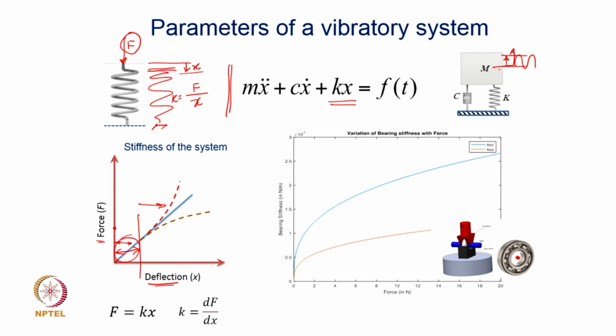And therefore, although it is valid for small amplitude vibration, you can definitely use this equation for your preliminary analysis. However, if your f of t is such or your parameters are such that the estimated x turns out to be much larger in amplitude, you should come back here and check whether it is going into a nonlinear regime, and if it does, then you should come back to this equation and reformulate it with the restoring force being formulated as a nonlinear restoring force, and there are equations which govern the behavior in this region, and that should be used to evaluate the response.